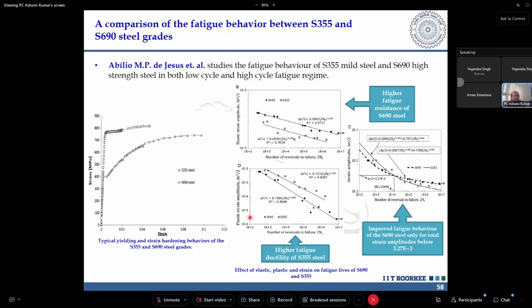And here is plastic strain amplitude, which means this is a low cycle fatigue where I have pushed the material into the non-linearity, I have applied the cyclic loads, and I have assessed the low cycle fatigue capacity of that particular material, both these grades I have assessed. You look at where the graph is lying, the SN curve for the high strength steel is lying above the low strength steel, which means right now you are happy in stating that, okay sir, that confusion was also removed,